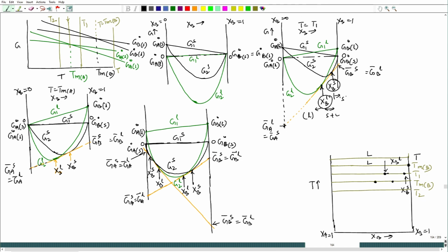Now, this solution model, the regular solution model, has been taken up. So, that is one assumption we have considered, that both have the same crystal structures. So, that means the solids on both sides which are coming due to the common tangent rule are the stable phases of solid of composition X B S.